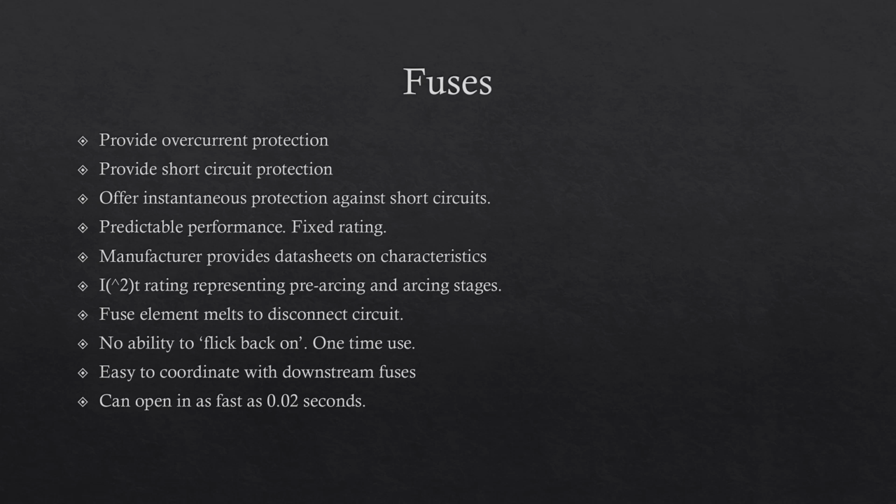Great thing about this: your fuse is blown, you can't just flick it back on, not like a circuit breaker. That means that if somebody tries to just turn the circuit back on, like a light switch that's turned off, they can't do that. It ensures that the actual issue is going to be remedied without possibly causing further issues by introducing the fault back onto the network, even if it is momentarily.